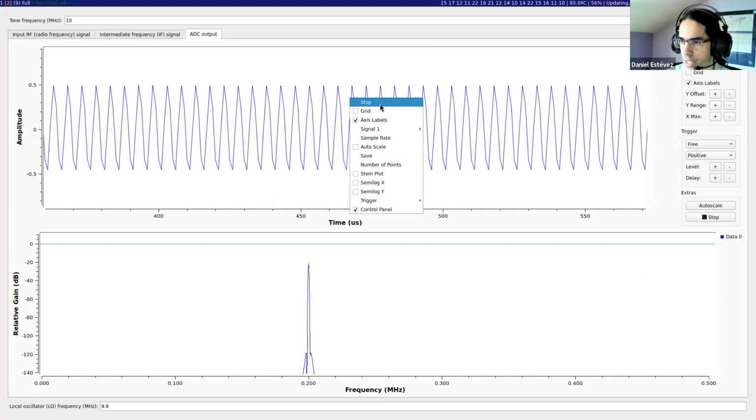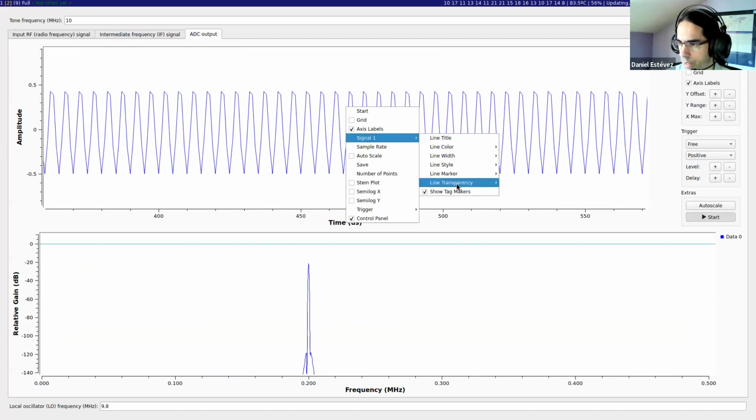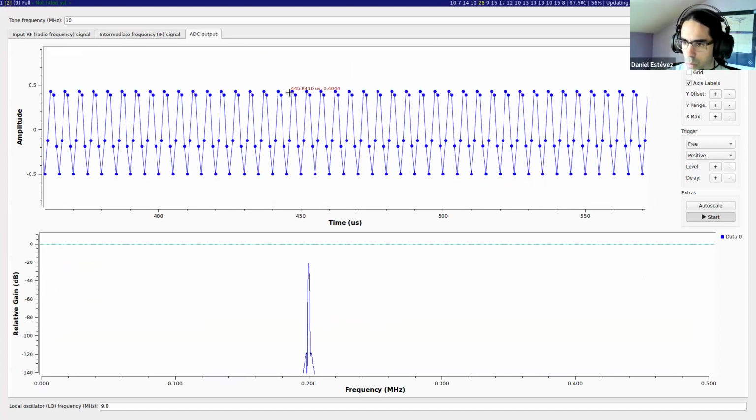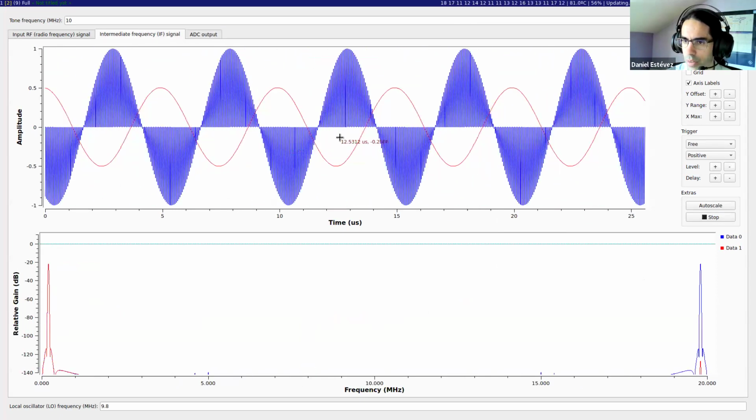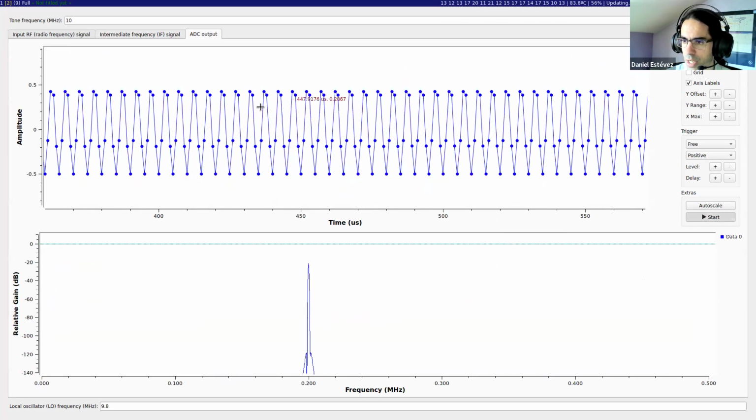And as we can imagine, the signal here, we don't have many points per cycle. Whereas here with 40 times as much sample rate, we have many more points per cycle, and so it looks like a smooth cosine function. But really, all the information about the signal being a cosine function is in here, even though this looks a little bit awkward.